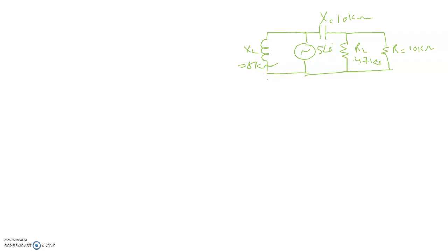So basically in Thevenin's theorem we try to reduce the circuit around two given points. We take A and B, the two terminals, and we have to reduce this circuit to this form. So there would be a source, and it is connected in series to an impedance. Let it be called ZTH. This is VTH.